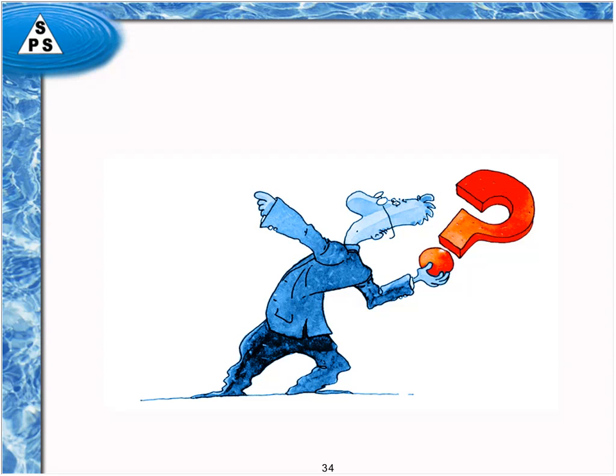I'd say that you're probably better off doing it more frequently than less frequently. And remember that even if you do hot water sanitize the system on whatever frequency, that does not eliminate the need to do a chemical cleaning, because you will still need to clean away some of the inorganic deposits, the scales, and certainly some of the accumulated organic debris, because it's not all biofilm that accumulates.